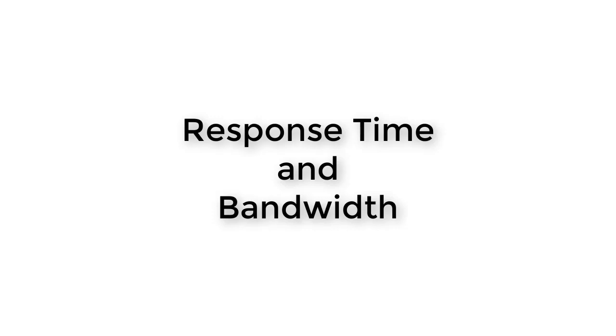Bandwidth tells us how fast the input can change repeatedly, and we will still be able to read the output. For example, suppose you take the potentiometer and turn the dial back and forth at, say, 1 back and forth cycle per second. Your PSOC and LCD screen might do a fine job of following your motion. Now, suppose you start to move the dial back and forth faster, 10 back and forth cycles per second, then 100, and so on. At some point, the PSOC and LCD screen will no longer do a good job of following your motions. It will start to read the amplitude of your motions as being smaller than they actually are. And when you get fast enough, your motions won't be read at all.